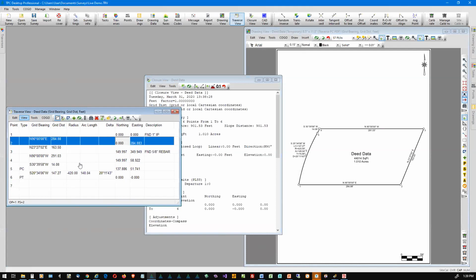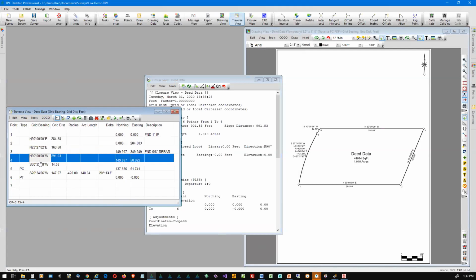Now, you can always check and see what's in your raw data. If I go to View, here's Display Raw Data, and Shift F9 is the hotkey. I use this a lot. Shift plus F9. So if we look, these are all going to be slightly different. I'm going to use Shift F9. See the difference? You're going to see little differences along the way as we toggle between these. Okay? So you can always view your raw data.